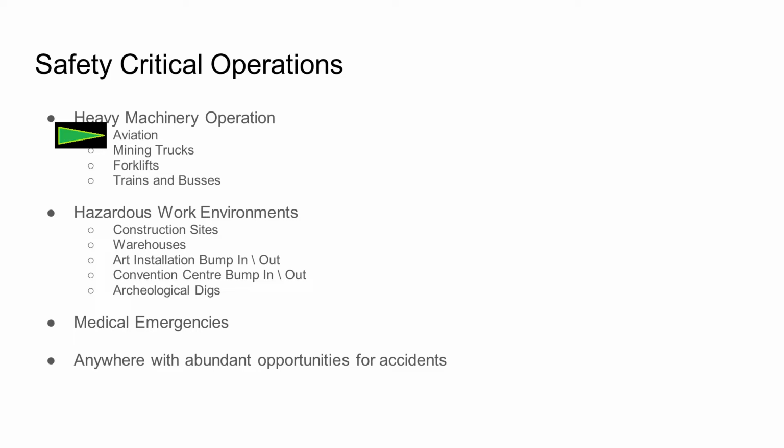You've got to do your final checks. They put it into acronyms so you remember. One funny one I'd like to share is BUMPFISH. You go brakes, undercarriage, mixture, fuel, instruments, switches, and harnesses, and I think also hatches. But yeah, you need to be checking this, and you need to be doing this all at the same time as listening out for the radio. You might possibly be communicating, and then also looking out for other traffic.